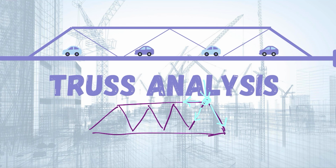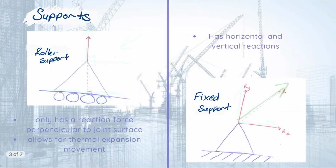So each truss will also have supports. There are two different supports you can have. You can have your roller support, where there are wheels at the bottom of the support, usually indicated by little circles like that. And this basically means it can move from side to side. So any reaction force it creates will always be perpendicular to the horizontal surface it is on.